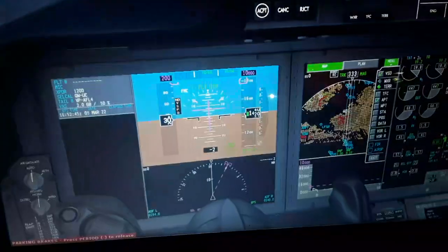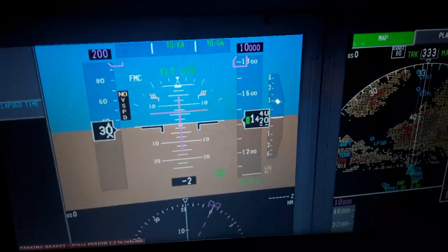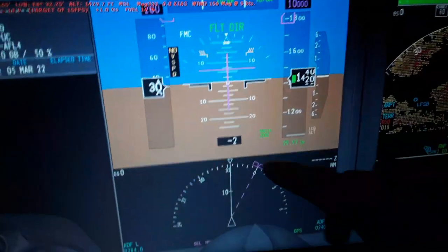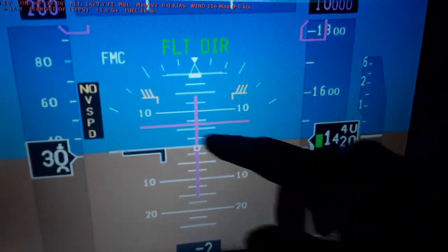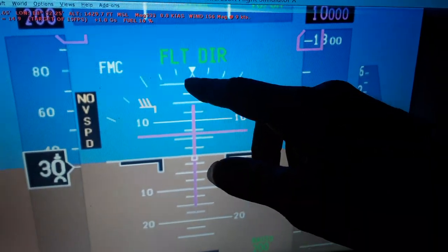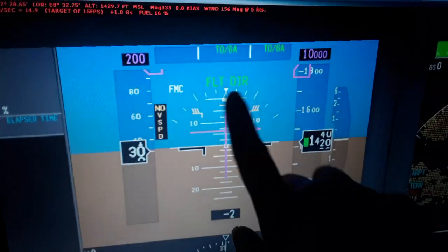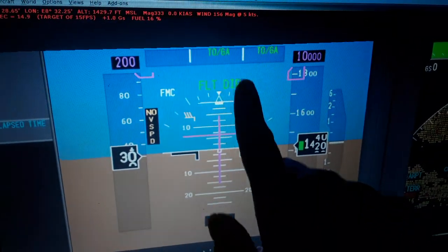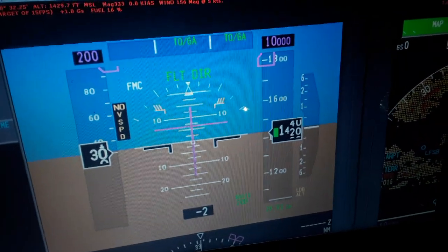The angle of attack of the aircraft as we fly. You can see the radio altitude above the ground level is 2 feet. So we have also the pitch attitude here. You can see 2.5, 5, 7.5, 10, 12.5, 15, 17.5, 20 degrees for pitch up or pitch down. Also the bank roll of the aircraft as we fly, how many degrees we can bank roll. The flight mode annunciators, the autopilot and the auto throttle. Later on vertical navigation mode.